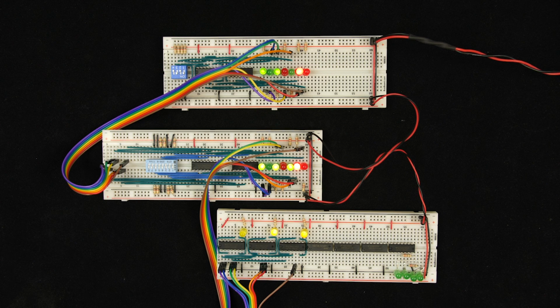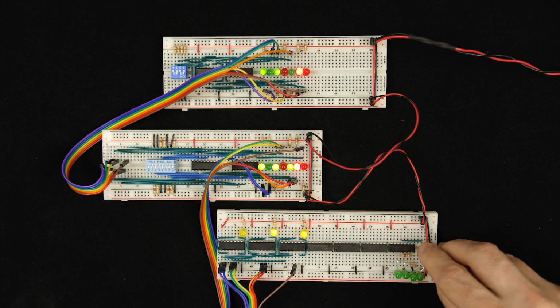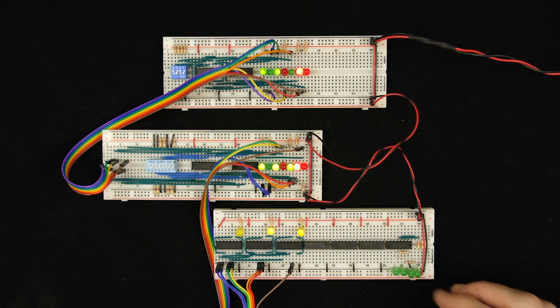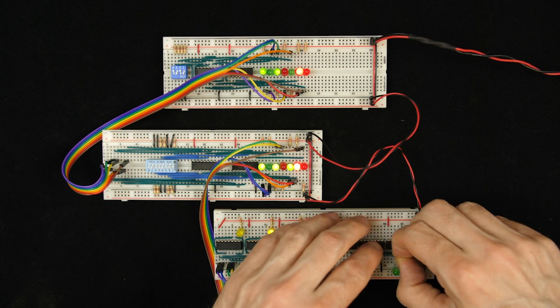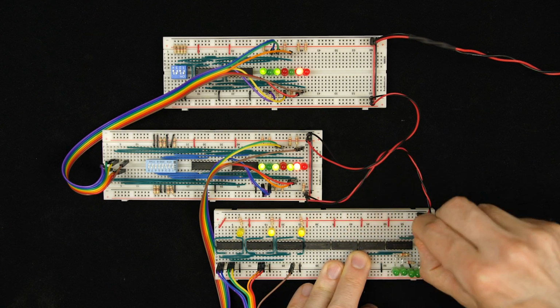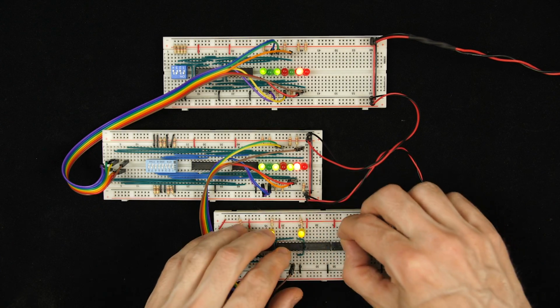So there's 4 XOR gates in this last chip here. And I'll just connect one of these LEDs up to the outputs of each of those 4 XOR gates. And I'm connecting them through just a 220 ohm resistor. So there's some extra current limiting through the LEDs. And I think what I'll do is just kind of work backwards, connect these inputs from the 4 XOR gates to the outputs of the 4 AND gates.